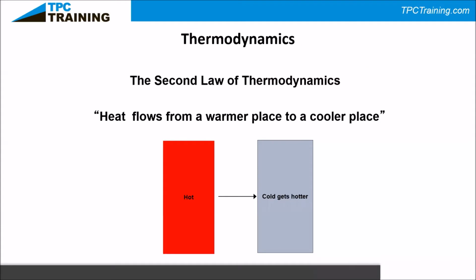So the refrigerant in the cycle never goes bad. It always is in there. And the only reason we need to replace the refrigerant is if there's a leak in the system or mechanical failure. Otherwise, there are units that can last 30, 40, some 50 years with the same refrigerant continuously if they're maintained properly. Now, I just want to touch base a little bit on how we size an air conditioning